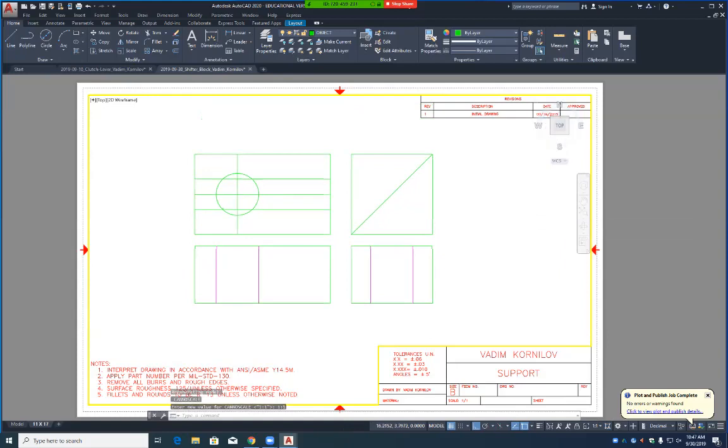So when you have a slot, I want you to dimension that way. This is showing you how to dimension it. So it's not pulling the measuring tape off one side of the thing, 1 inch overall. No, we're going from the center point. It's 1 inch plus or minus, with a 1/2 inch from the center point. It could actually be larger, from the center point.